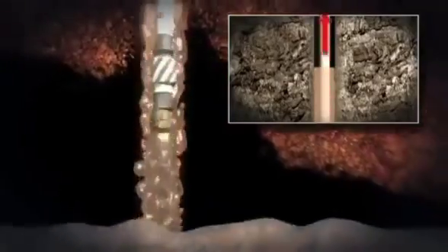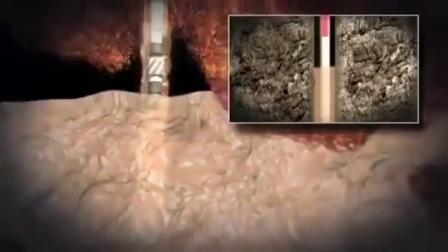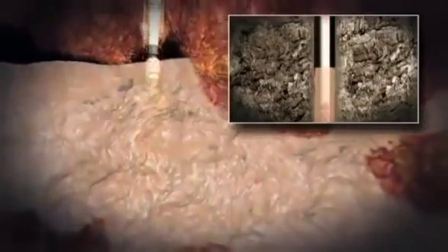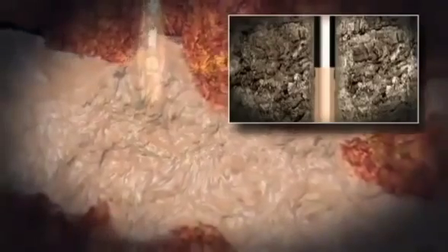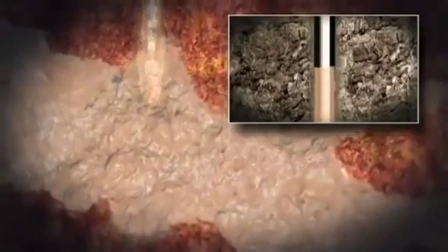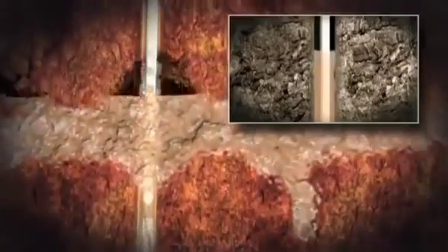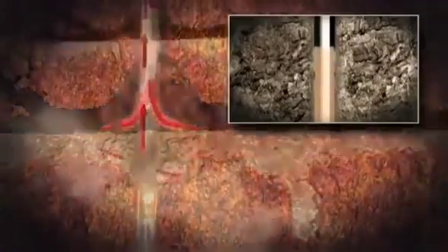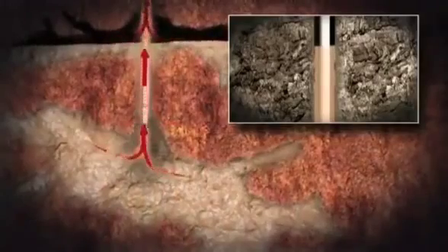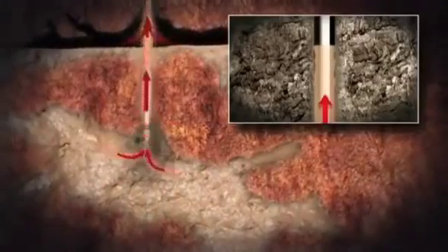Lost circulation material is added in an effort to seal the lower fractures, which allows the mud weight to be increased in an effort to control the kick from the upper fracture zone, resulting in a new round of fluid loss in the upper zone. This cycle defines a typical kick loss scenario that creates many problems.